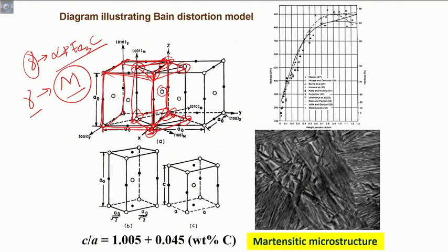So, now we are looking at the formation of a new unit cell out of the existing FCC unit cells. From 2 neighboring FCC unit cells we have squeezed out a new unit cell, whereby the length here is exactly the same as the length in this direction. So, the length is exactly a naught, but in the other 2 directions the lengths are now shortened, squeezed to a naught over root 2, because you can easily calculate that this length will be root 2 a, and half of that will be just a upon root 2.